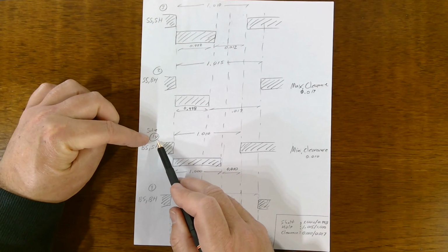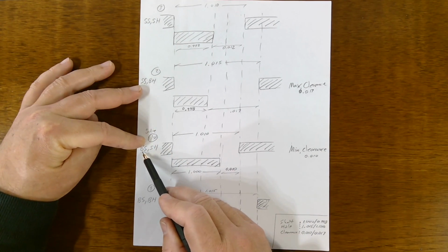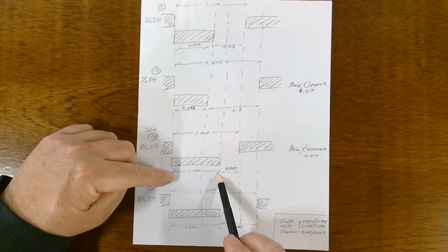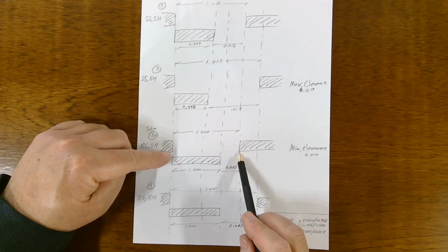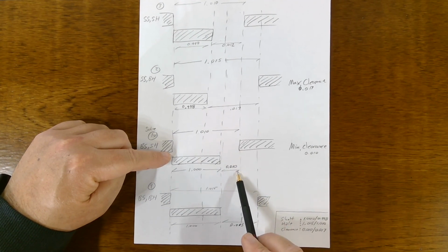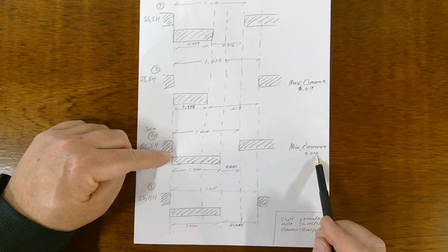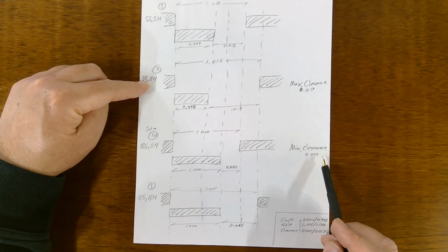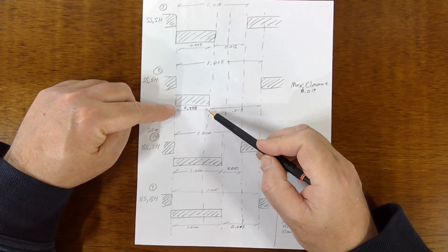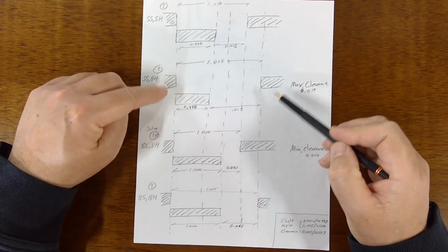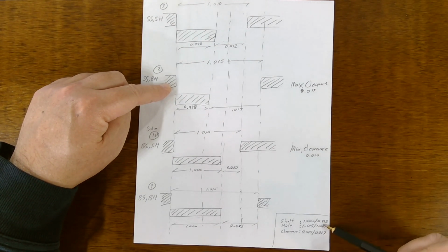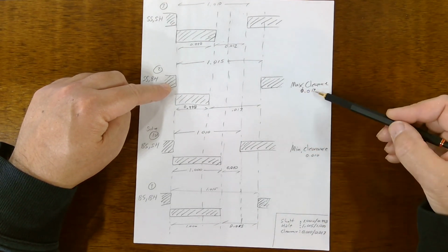Do this first. This is the situation of biggest shaft, smallest hole, right? Biggest shaft is 1, smallest hole is 10. The minimum clearance would be 10 thousandths. Okay, then do this one next. This is smallest shaft, biggest hole. Smallest shaft is 998. Biggest hole is 015. Just using these numbers of smallest and biggest, I end up with a maximum clearance of 17.